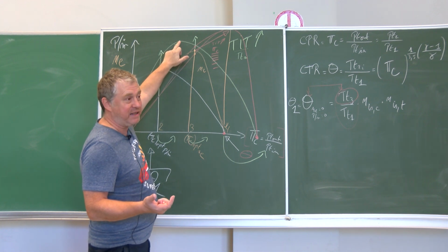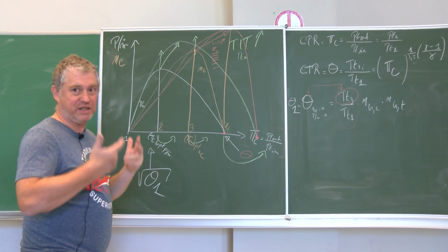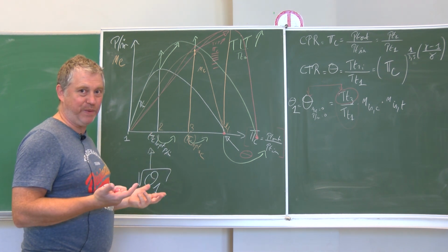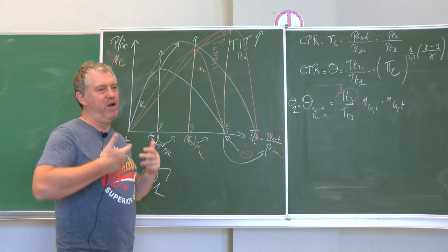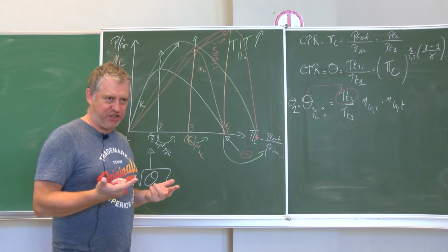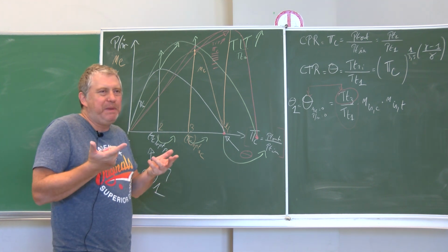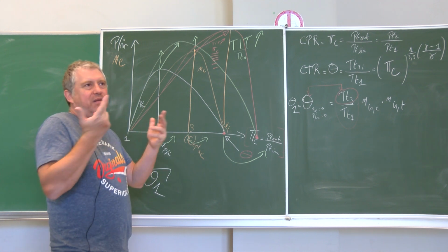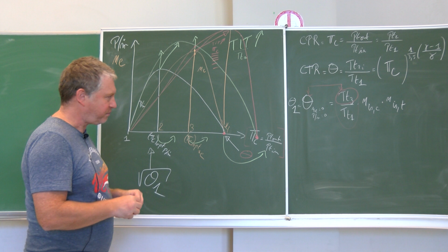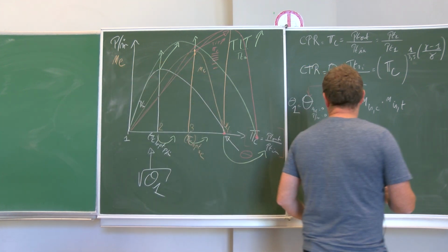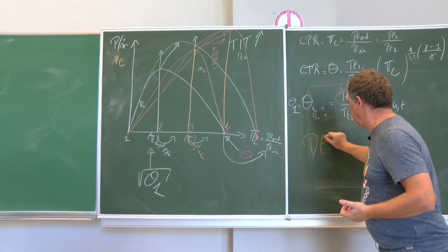You will increase the TIT, also increase the pressure ratio, but much less, because it's remaining at a low pressure ratio. So when you need to have a lightweight engine, you will have, let's say, a small compressor. What seems to be rather logical, but it's obvious when you look at the thermodynamics. And like this, you can define your design point.